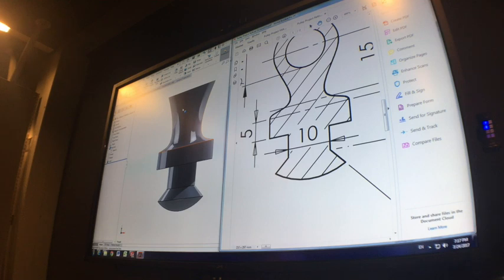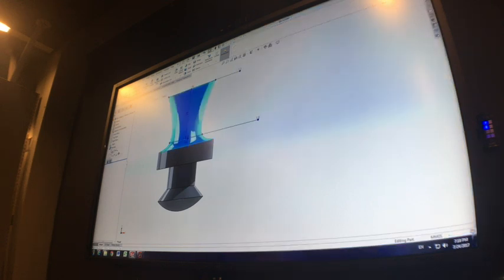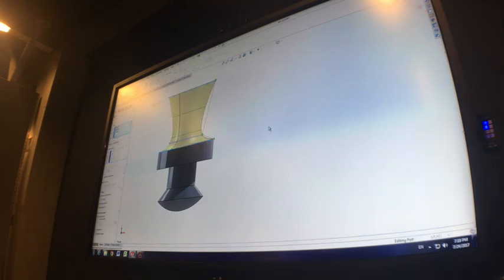So there's settings that we can control in our loft feature. We haven't done much of this going back and editing features yet, but if you ever need to edit a feature, you click on that feature in the feature tree, and you click this icon here, edit feature, and then you're able to edit the settings of that feature. Okay, so if it's an extrude or cut, you can change the thickness or the depth. If it's a revolve, you can change the amount of angle.